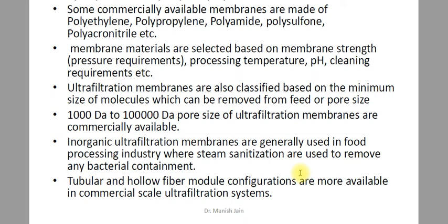And if you are concentrating or clarifying fruit juice, meaning removing the different types of microparticles present in the juice, you have to be conscious that bacteria should not start to grow on the surface of the membrane. For that you have to use steam sanitization at different time intervals.